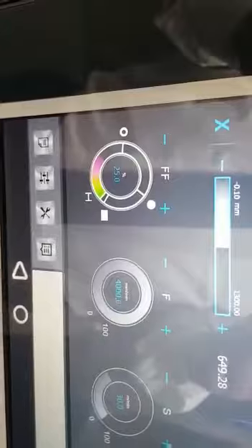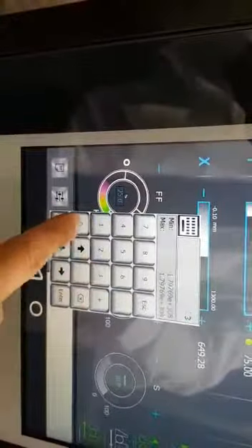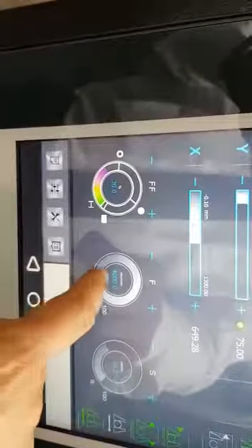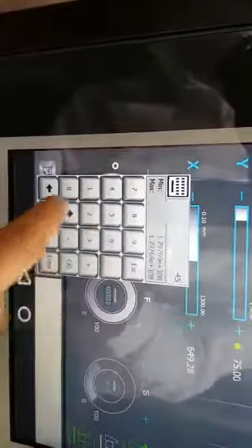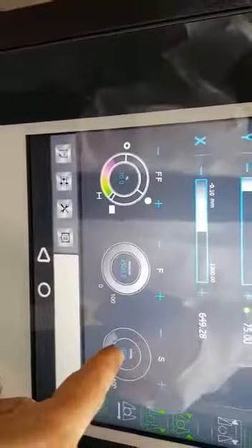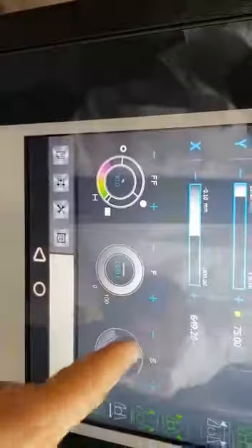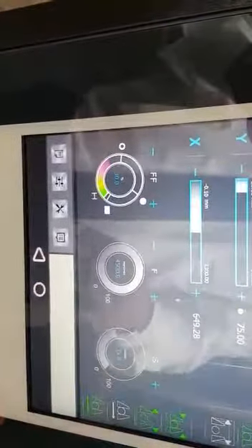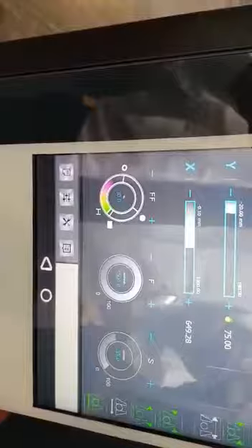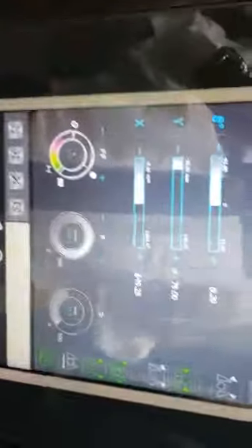This is the nice part I think we've really done up. This is the feed rate, so your amperage control. You can modify that at any given time. Your feed rate, so if you want, let's say the 4,500 mil, we want to crash the blade in, you can do that. Or you can modify the 35 meters per minute, okay? Plus or minus, again, you can adjust those values. Now remember, all these values can be preset from your computer directly to the machine, all right?